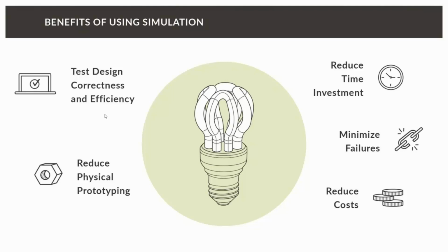And I think the other point as well is minimizing failure. So the flow can move pretty fast through these things, and if we can minimize and hopefully avoid cavitation, we're going to reduce erosion, and we're going to increase the lifespan that the turbine would survive for. So again, just through using CFD, and it does a lot behind the scenes. It's easy to use, but there are very huge calculations going on behind, so we can predict and give you an idea of where fluid might cavitate, and then we can reduce failures and improve the lifespan of the model.